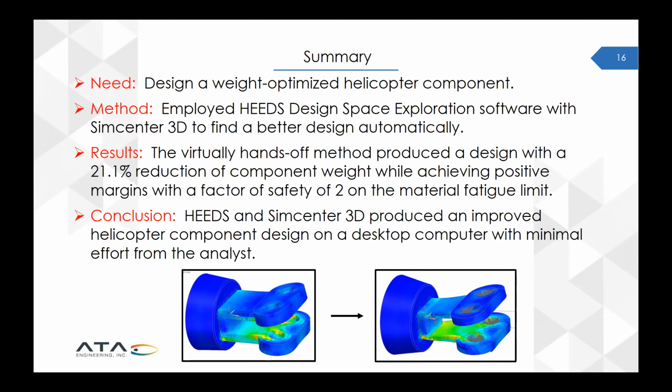So it takes a little bit more work up front by the analyst to say, okay, these element IDs are in a range that would have these stress hotspots, and if you could just ignore these and concentrate on the more realistic stresses, then that wouldn't affect the optimization.